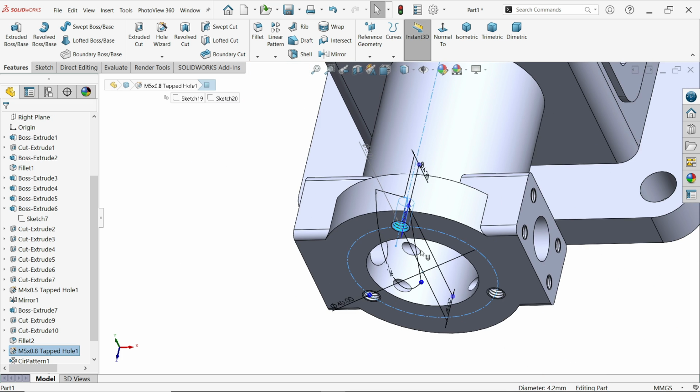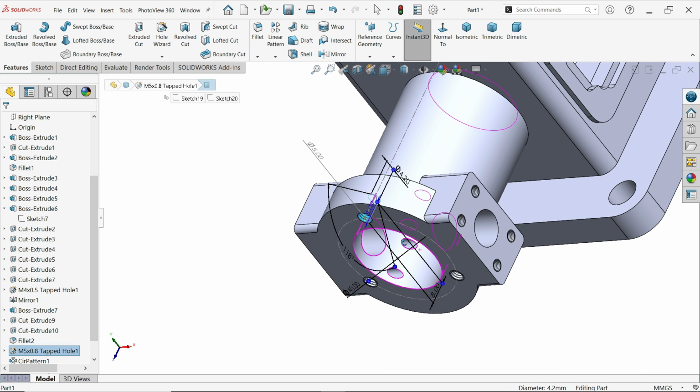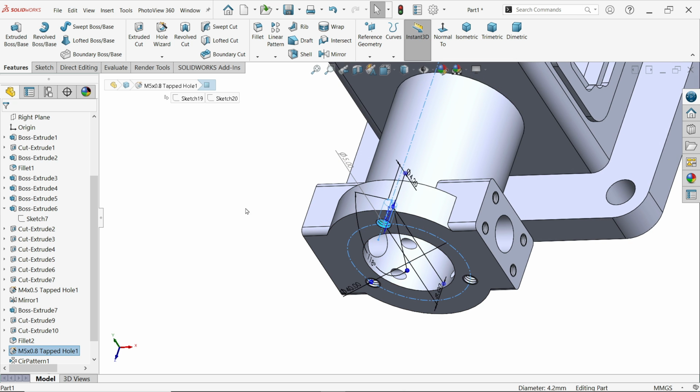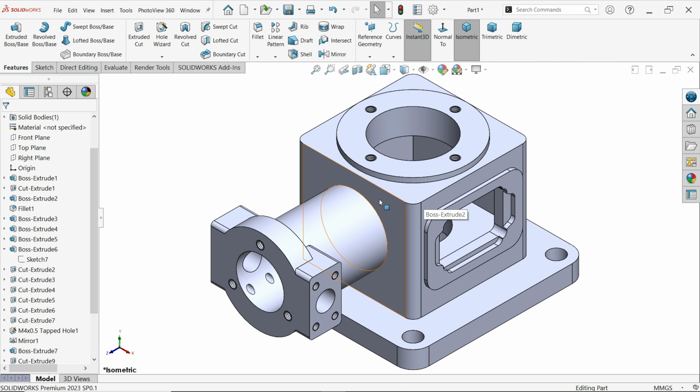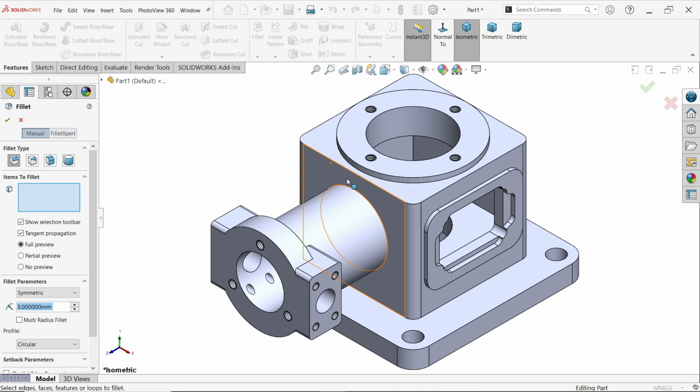Let me check either this hole depth. Okay, perfect. Even though, let's activate fillet, 2 millimeter constant type fillet in drawing, 1, 2. These are 2 millimeter, as shown.